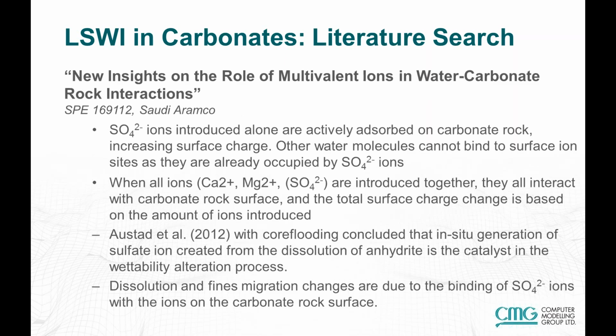Now this paper from Saudi Aramco concluded that the SO4 ions introduced alone are very actively absorbed onto the carbonate rock surface, increasing the surface charge. However, other water molecules cannot bind to the surface ion sites because they're already occupied by the SO4 ions. In another experiment they did, with all ions introduced together, they all interact with the carbonate rock surface, and the total surface charge change is based on the amount of ions introduced.